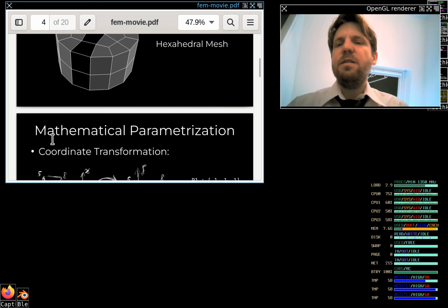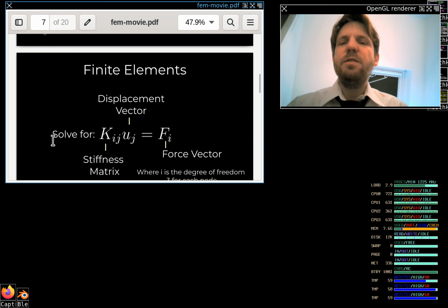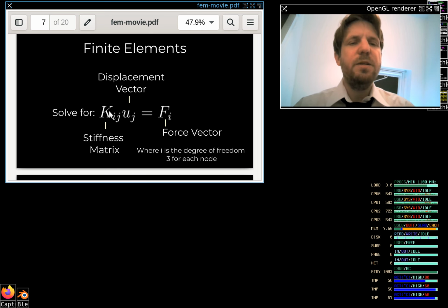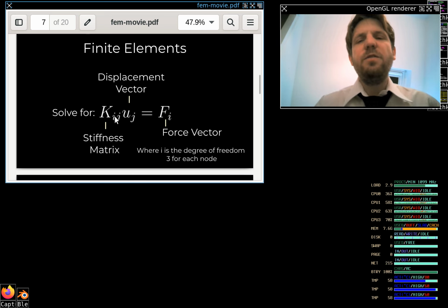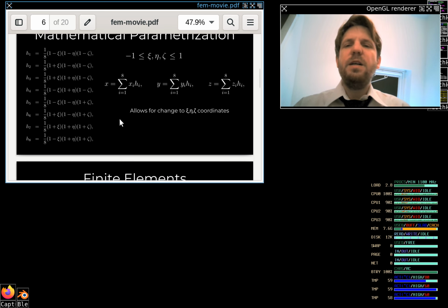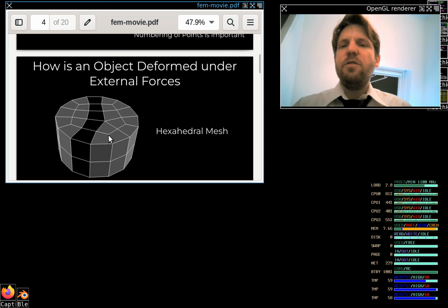You can just linearly sum this, so you calculate one element after the other, the stiffness matrix for one single element, you sum it at the right positions here, and this basically works. Of course, you know that ij are shared by elements, because there are several elements that share this point. This point here is shared by at least 3 elements, this element, and this element, and this is a point ij in the stiffness matrix.